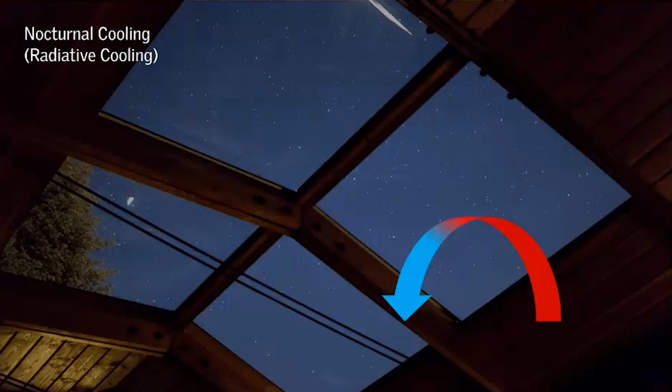skylights. What that is: warm air goes up to the skylight, it cools, and then it drops back down. So you're actually feeling some cooler air dropping away from the skylights. That convective current is going to feel like a breeze. So this is another reason to have higher performing skylights, or as we saw in the image I showed with the Danish installation where they had the heater, providing some heat close to that skylight to reduce that sensation. But higher performance skylights reduce your risk of that happening.